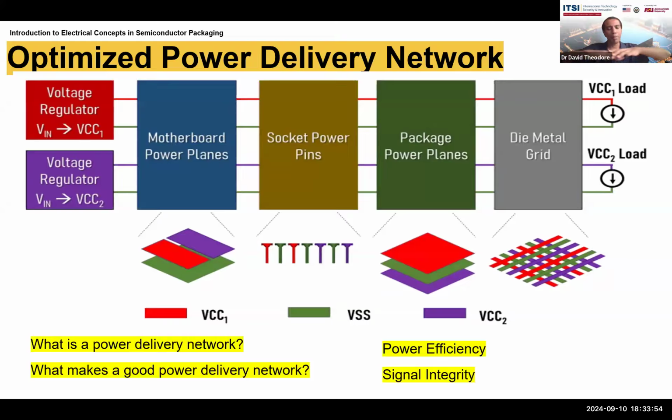It can either be a metal sheet or it can be a patterned metal layer. Then above this, we have the next layer of metal that's isolated from the other, where either it's a sheet or alternatively it is thick lines, like buses that carry power. So this will not be a solid sheet, but it'll be basically a patterned sheet that carries power from the outside to the inside and so on.